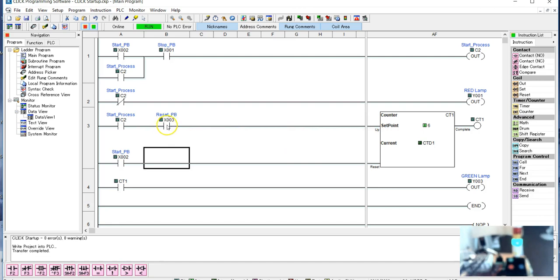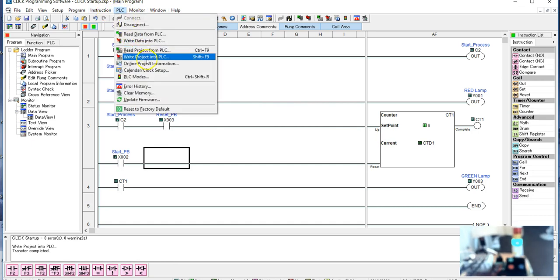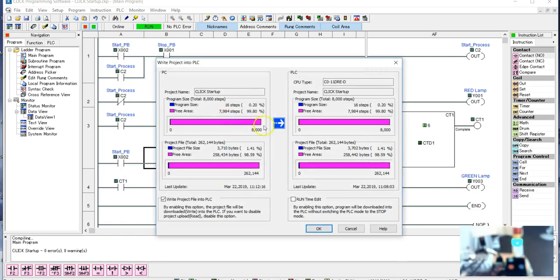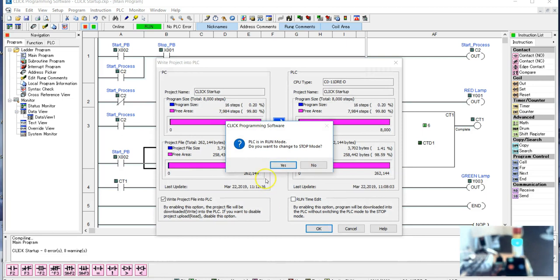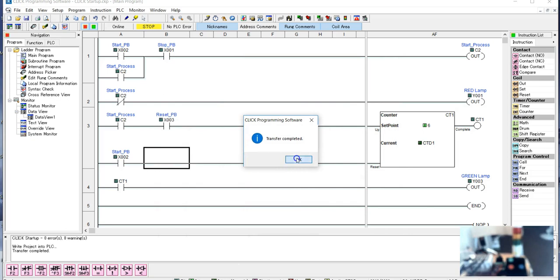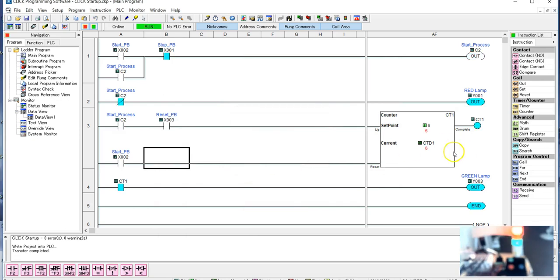but now I won't have that initial problem where it automatically counts to 1 the very first time through. At least that's what I'm thinking. So let's take a look at this and see if that does the trick. When I push this in here, actually this will do two things for me, because now when I turn it on, we have 6 in here. When I hit my initial start push button, that'll reset it to 0 and it'll set up my start process, but it won't make that initial count. So let's see if that'll work.